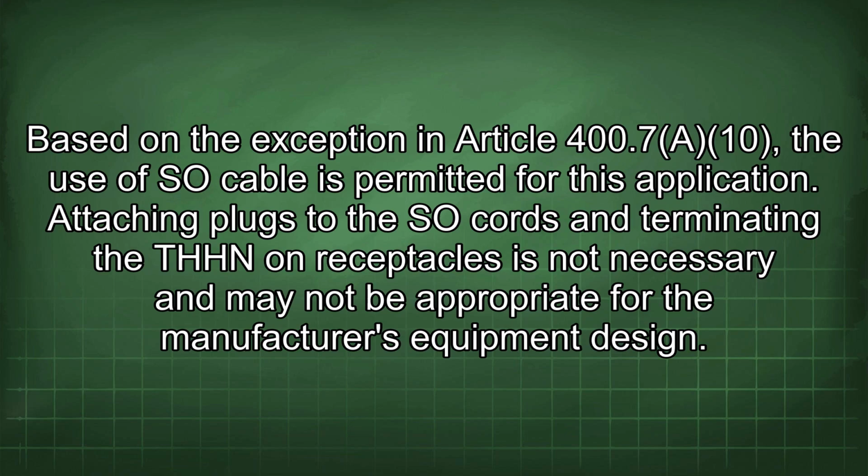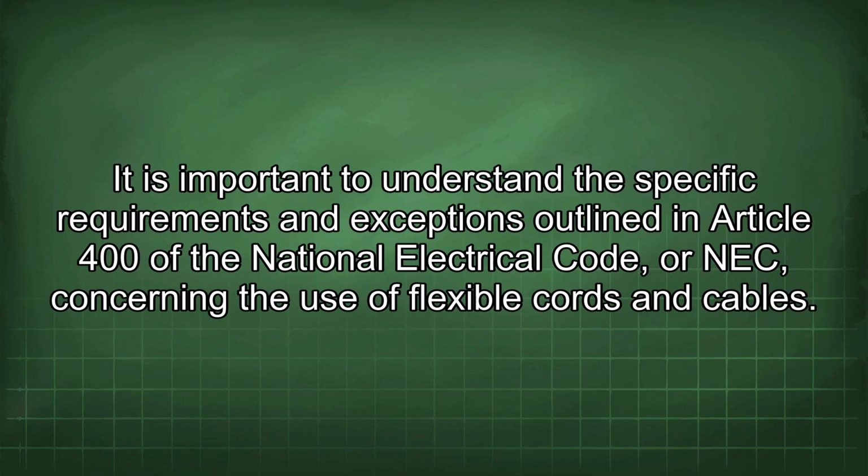Attaching plugs to the SO cords and terminating the THHN on receptacles is not necessary and may not be appropriate for the manufacturer's equipment design. It is important to understand the specific requirements and exceptions outlined in Article 400 of the National Electrical Code, or NEC, concerning the use of flexible cords and cables.